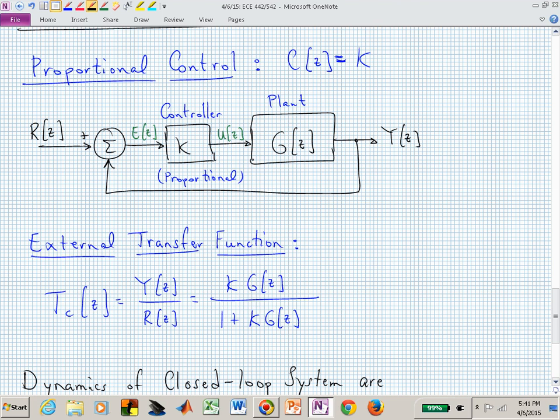So you might have a PD controller, and in this class we will probably always just assume these ideal scenarios, but a PD controller in the ideal case has a pure derivative, and you really don't want to be doing that. If your error is any bit noisy, now you're differentiating this really messy signal, and you're making it even worse by differentiating it.